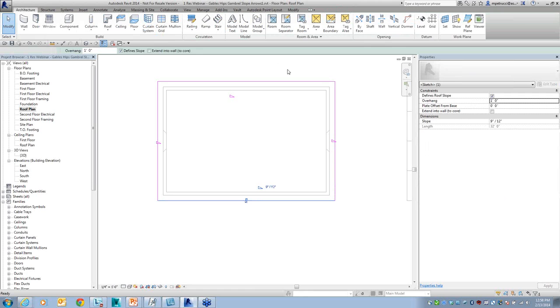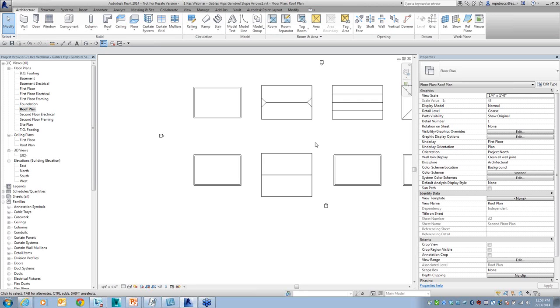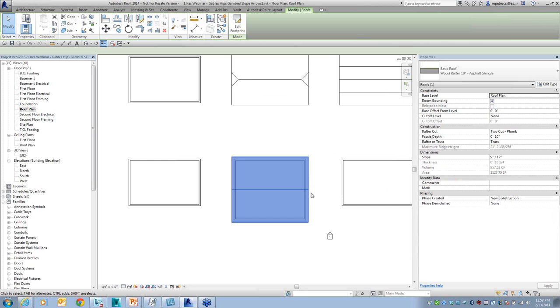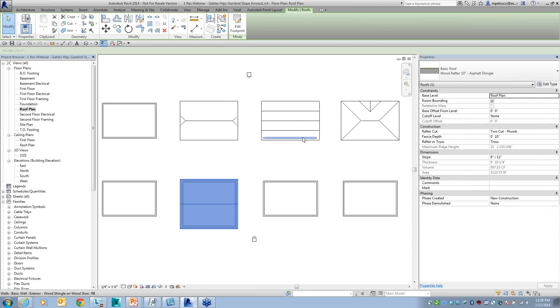It'll finish this off. And same thing would apply down here. I realized I also made this building a little bit wider, which kind of threw me off. So easy enough, I can fix that. So next thing we'll take a look at is this mansard roof. Now the mansard roof, this one I will have to use slope arrows.